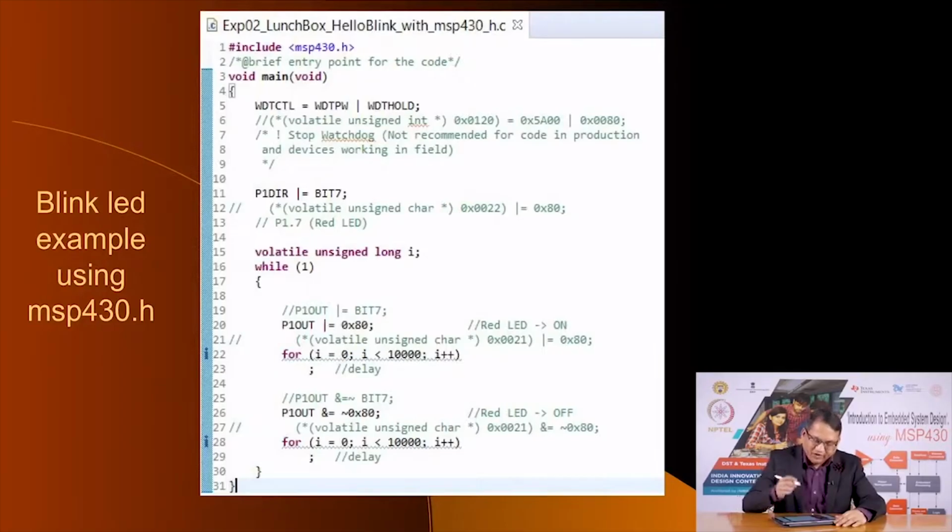For that we have to tell the microcontroller that such a LED is connected to such a port which has a certain name, and as we will see when we deal with the MSP430 architecture, these ports on the MSP430 G2553 microcontrollers, there are 2 ports, one is called P1, the other is called P2. And in our case we have connected an LED to bit 7 of port 1. And so we are dealing with those ports using a name.